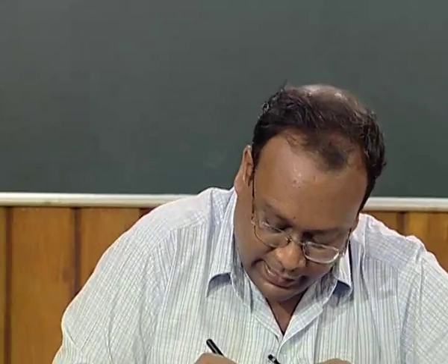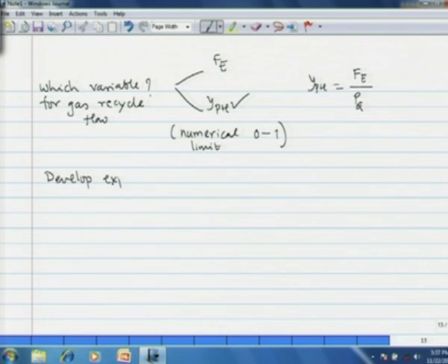So, it helps in doing material balance if we use YPH as the design variable. Okay. Now, we try to develop expressions for PG, purge gas, and FG, and this will be in terms of the design variable YPH.